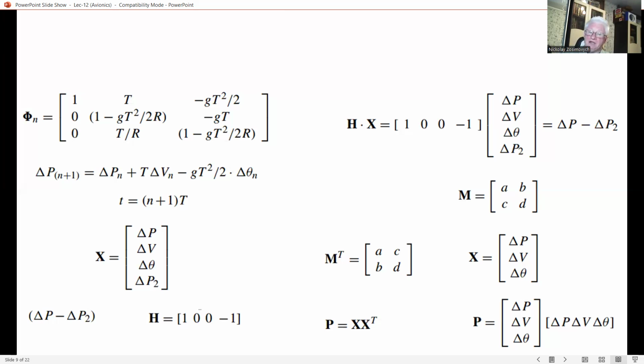The barometric altitude information from the air data system is combined with the INS vertical channel, as shown in previous lectures, in a baro inertial mixing loop. The GPS receiver error model typically comprises 12 states.